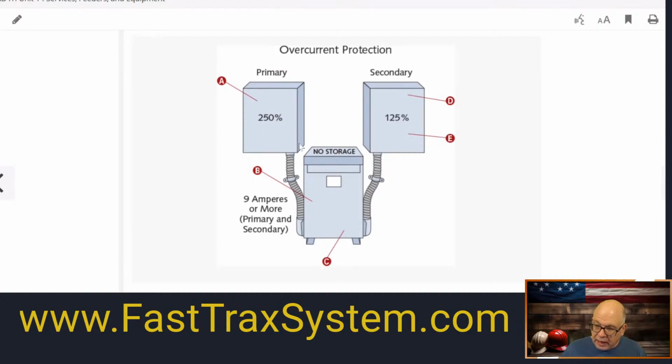Okay. And then on the secondary side, that same type of transformer. Now let's say the secondary is a 120/208. So in the same scenario, I'm going to take that 208 times 1.732. That gives me 360.25. And so I'm going to do 75,000 divided by 360.25. If you want, just use 360 to get you in the ballpark. And that's 208 amps on the secondary. Okay. So now that's not going to correspond with a breaker, right? And for 240.6(A), what am I allowed to do? I'm allowed to go up to the next standard size.